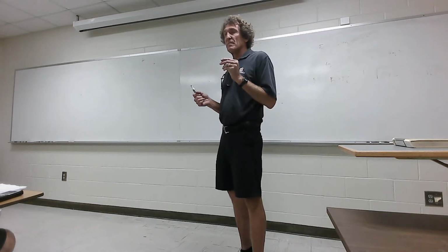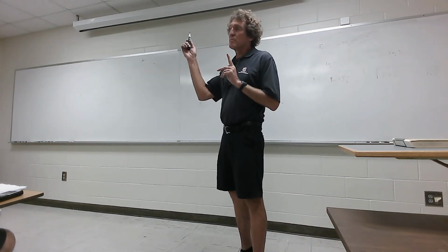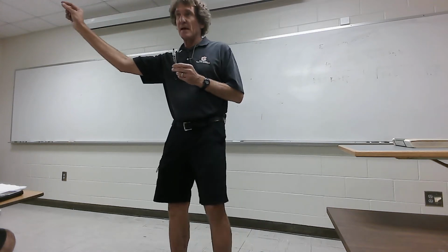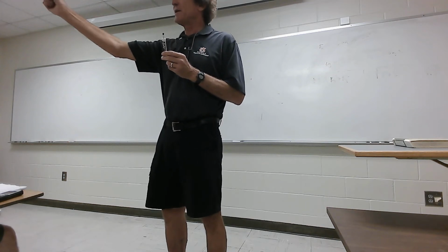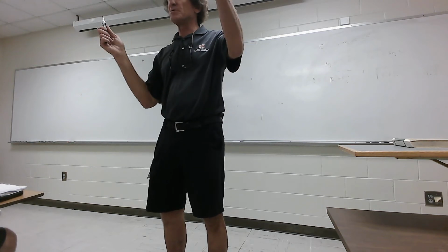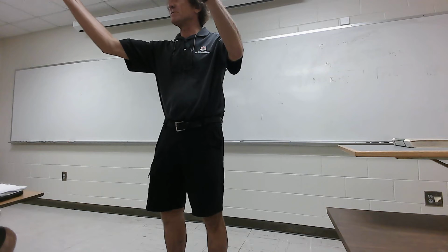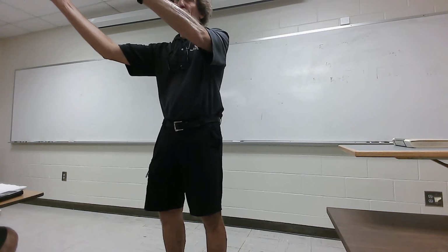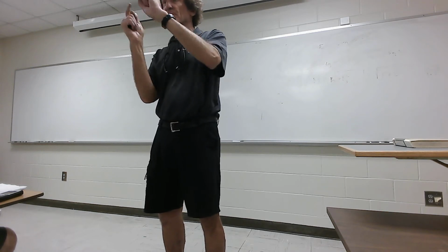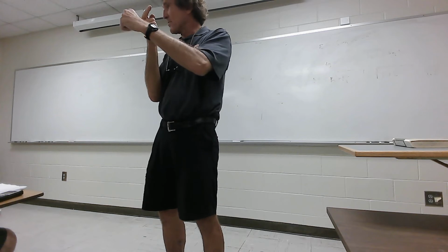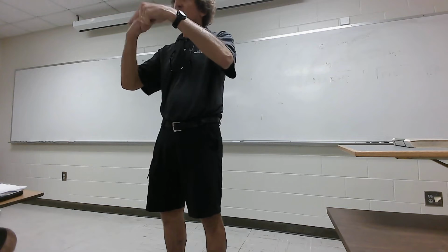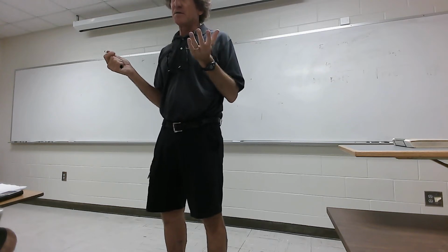Now, with a dielectric, no real conduction current moves from one plate to the other. And I mean by this, think of this as a thought experiment. If I could spray paint an electron blue, it would never move from that plate to the other plate. That electron can't move through there. But what it can do is induce charge in the other plate. So if I have a lot of positive charge on this plate, it induces negative charge on this plate. And in doing so, it causes the dipoles of the dielectric to flip back and forth. Now you have microwaves. You know, microwave heating simply takes the water molecule and flips it around and causes thermal energy, right? It dissipates energy that way.